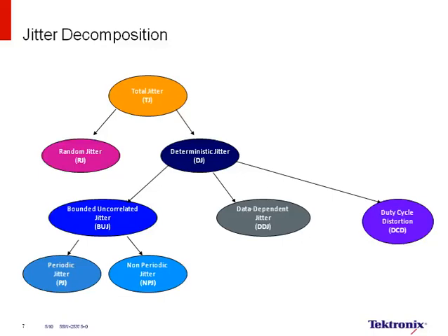Understanding these can help one determine where the resources should be spent to bring the overall TJ, or total jitter, budget under control. Earlier, we had talked about how parameters like standard deviation can be used to determine the peak-to-peak jitter.